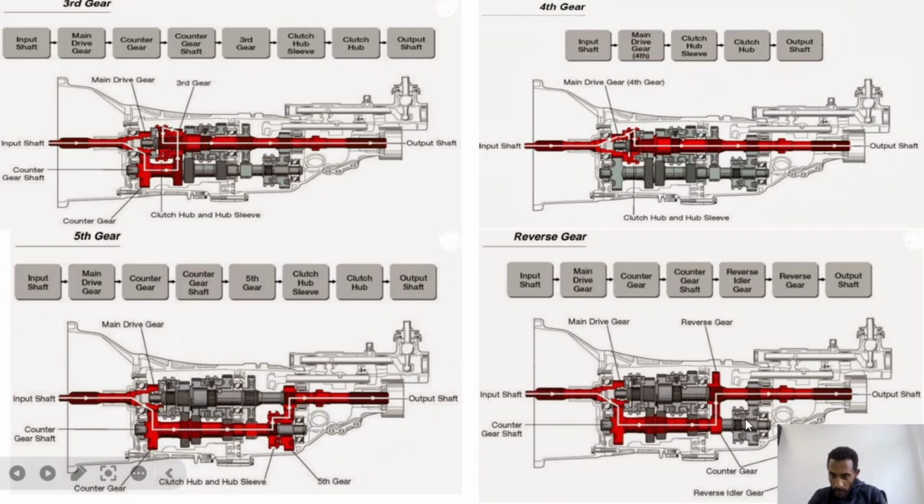In this part, what you are observing here is the revolver view of this picture. In this part, 3 gears are meshed for creating reverse, because this one rotates counterclockwise, the mating gear opposite, but this and this will have the same rotation. So to change the direction of rotation of the vehicle, to move forward or backward, for forward it uses 2 mating gears, for reverse it uses 1 extra gear. We call this the reverse idler gear, to change the direction of rotation only.